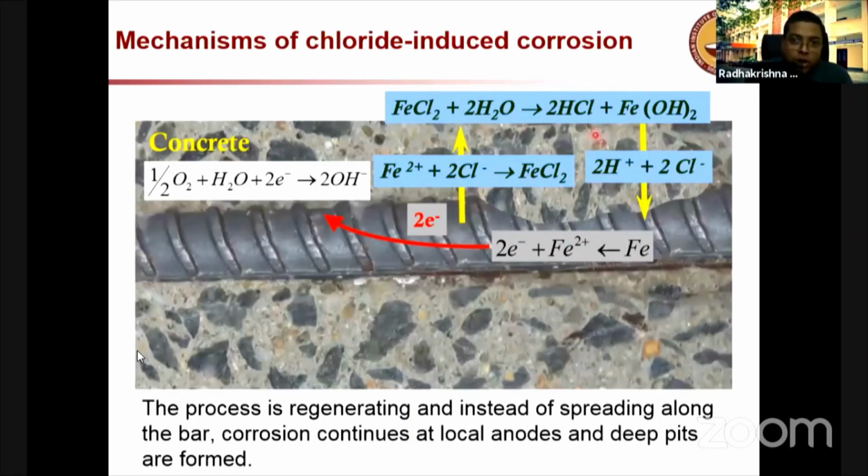So this keeps on going until you have sufficient moisture or oxygen available in the system. So that's why we say moisture and oxygen are essential for corrosion to continue. If you can keep your structure free from oxygen and moisture, you're very good. It will not corrode that easily, and probably not corrode. But that's very difficult to achieve. So for this slide, let's say this: as long as there are moisture and oxygen available, chlorides can continue to make more and more rust.